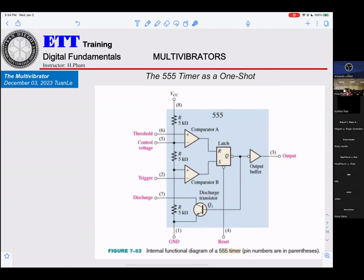Pin number 8 is VCC. Then pin 6, pin 5, pin 2, pin 7, pin 1, pin 4, pin 3. Pin 3 is the output. This will be the internal of the 555 timer. Now I try to help you understand what's going on inside.